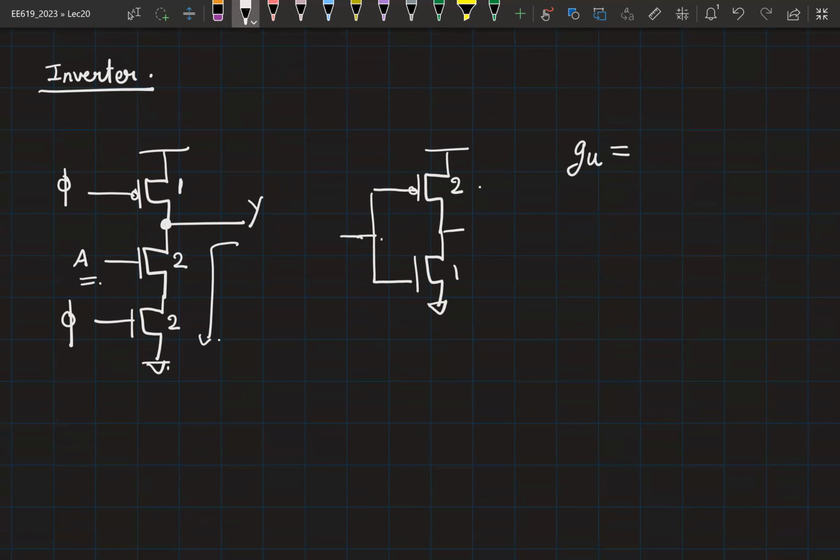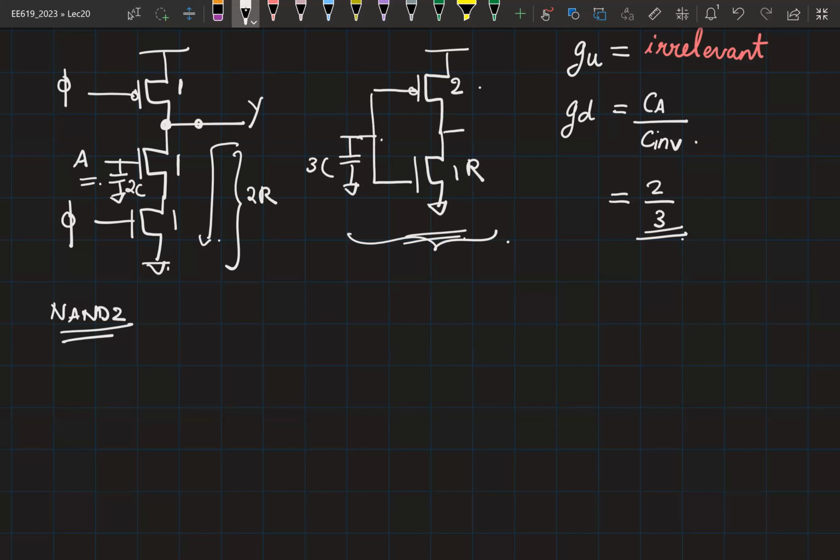So can you implement NAND 2? How would you decrease the delay? Increase the size of the pull down network. So you increase the size of the pull down network, your capacitance here will increase, right? So if the load capacitor being added is not very large, then you might not see much benefit. But if the load capacitor is large, then this is the sizing algorithm that we regularly use, right? You can upsize the pull down network so that you have larger drive strength and smaller delay.